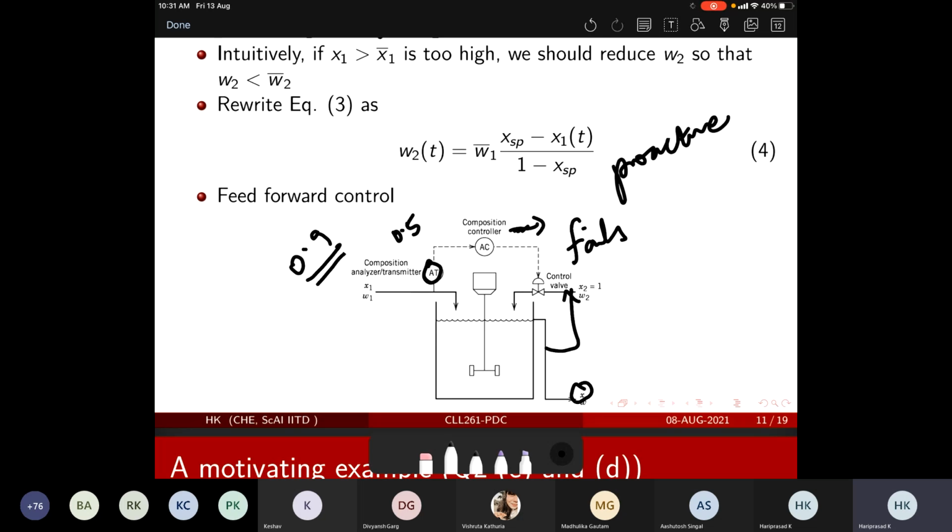Okay, this is now 0.9, so there is a large change I need to nullify by increasing or decreasing the flow here. Then you suddenly change it very drastically, but it was a sensor measurement mistake. It is possible because they are electronic equipment. There is a very high likelihood. Most of the problems in industry are related to instrumentation incorrectness.